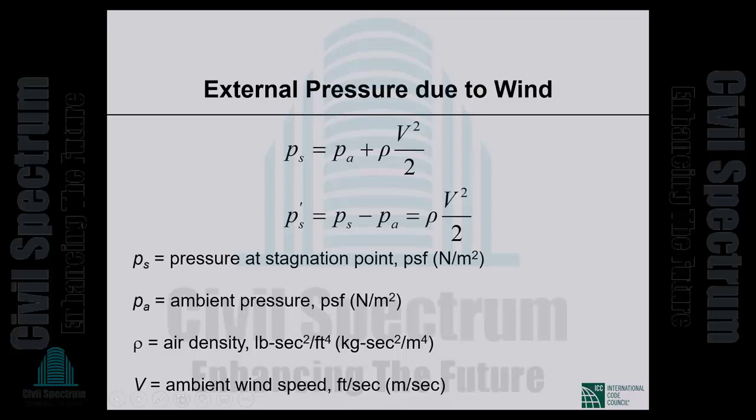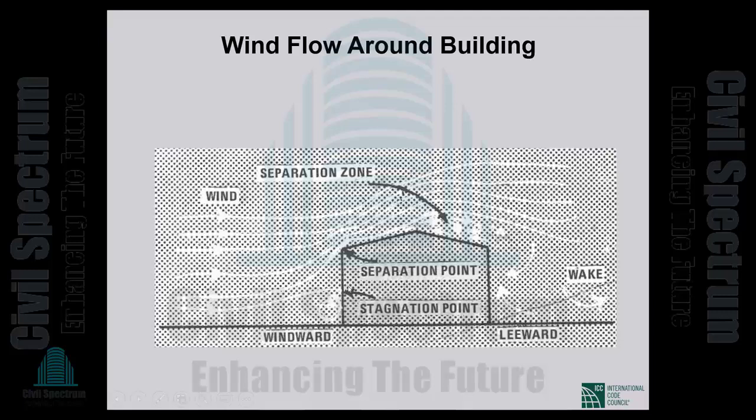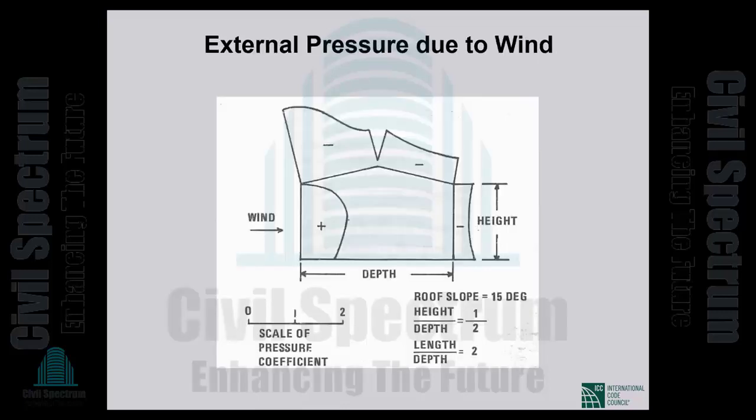I should say that near the center of the windward face, there is a point called stagnation point where the positive pressure is the highest at any point on the surface of the building. And the pressure there is called the stagnation pressure. That's the highest pressure experienced anywhere on the surface of the building. And the stagnation pressure is equal to 1/2 rho v squared from physics.